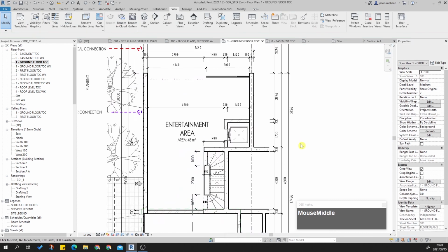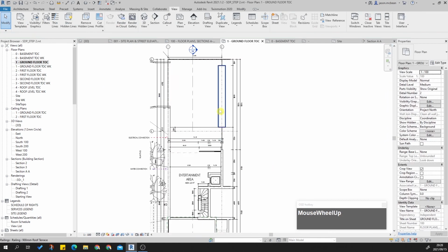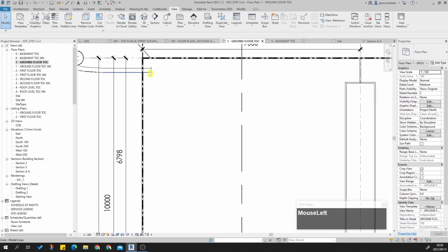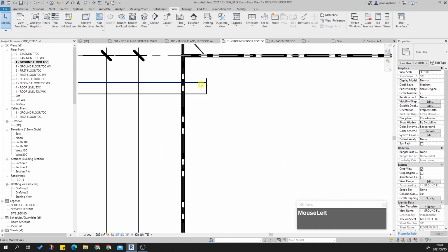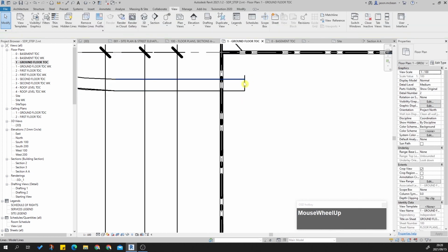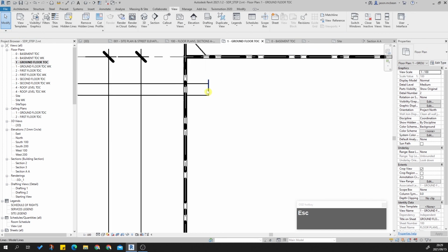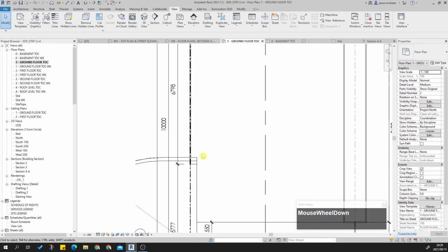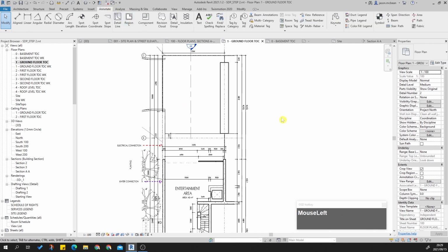So we've copied in some stuff from the site plan, and you can see this is coming together. Now we just have to add some additional notes and information. This is line work beneath, so technically we can start hiding this information. That's where the driveway comes in. But that is a model line, and technically it's on the ground floor, so we are going to see bits of it, but I'll explain a bit later on what we can do to make that disappear. We can use an annotate mask region to get rid of that.